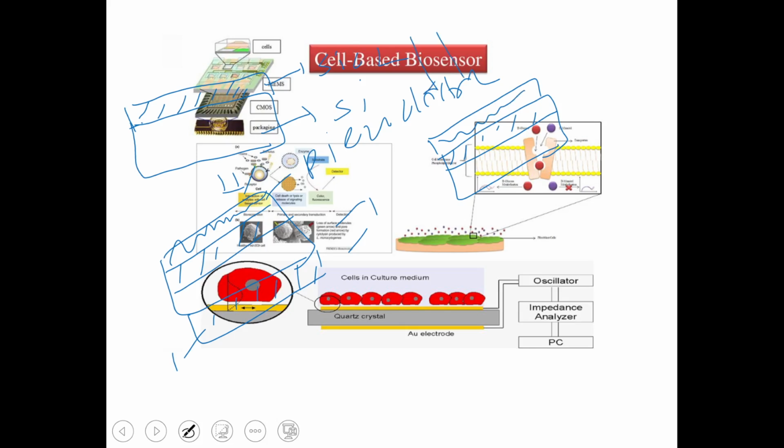Here we have to do the UV exposure. Some shadow mask, some design will be there. This will be transferred by the UV exposure. Then we have to do the etch and everything, soft baking, hard baking, whatever steps are required. We have explained that in the previous class, or you can go through that instructor on YouTube.